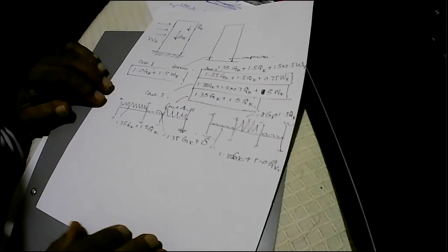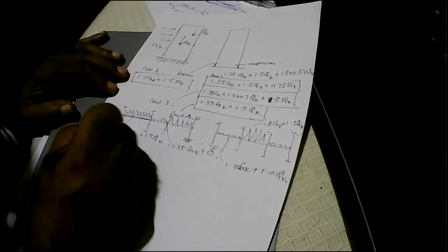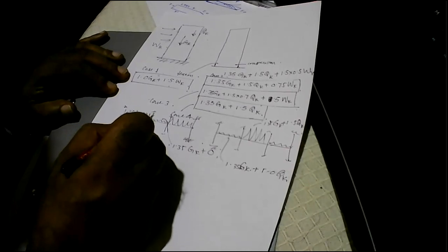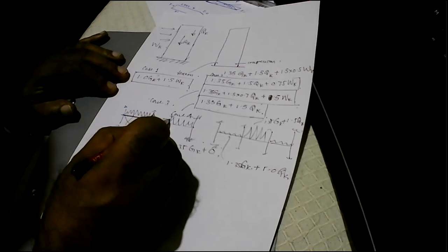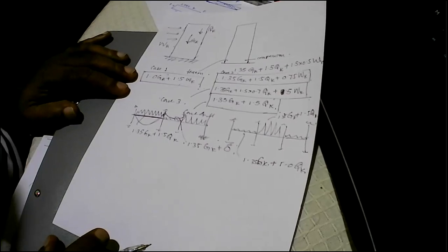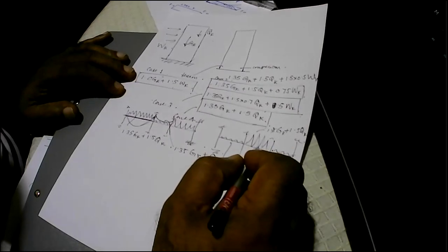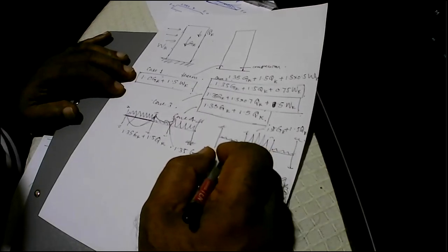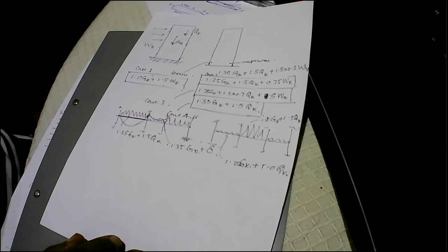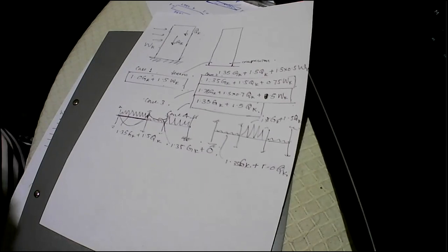So you have to create this, and when this is loaded with maximum, here you get the maximum sagging here, and when you get the sagging as maximum, there's a possibility that this span might go into hogging moments. And that's why we go with pattern loading. Then we load this on maximum and expect this to have the minimum moment here. So when you are considering the pattern loading, either you use 1.0 or 1.35, but whatever you use, you use it throughout all the spans that you are going to design.